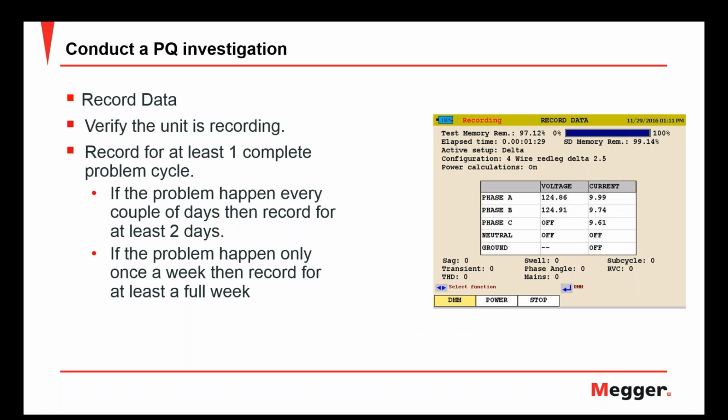And before you walk away, just make sure that that analyzer is recording. I cannot tell you how many times we've had people set them up, made sure everything was right, and then left, forgetting to actually start the recording.